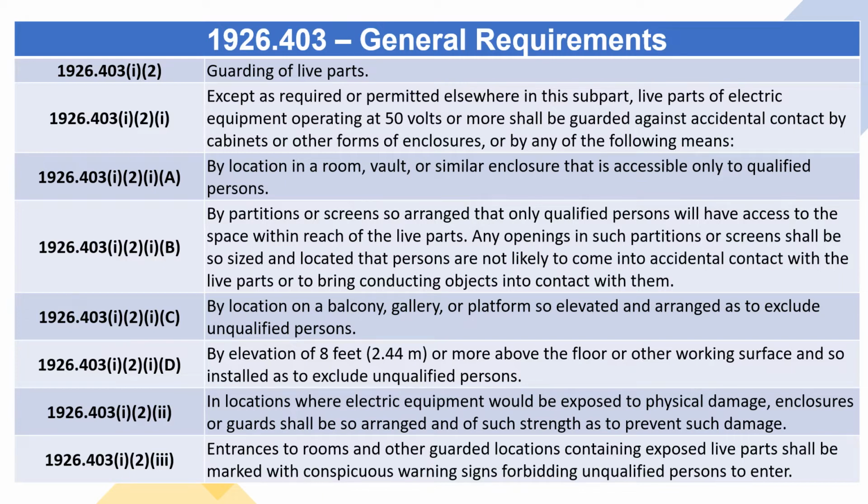(ii) In locations where electric equipment would be exposed to physical damage, enclosures or guards shall be so arranged and of such strength as to prevent such damage. (iii) Entrances to rooms and other guarded locations containing exposed live parts shall be marked with conspicuous warning signs forbidding unqualified persons to enter.